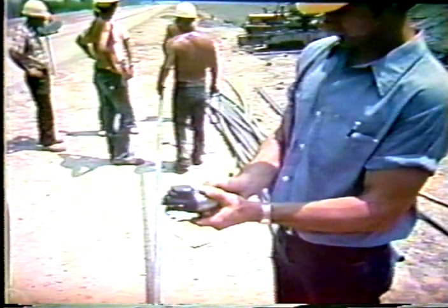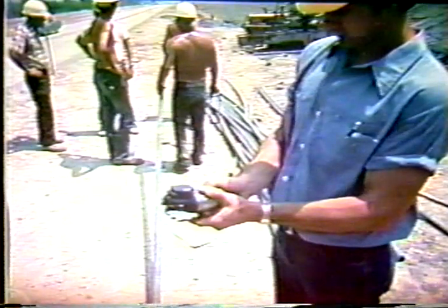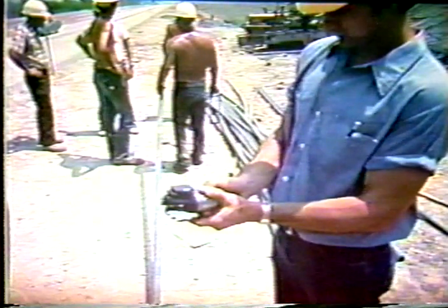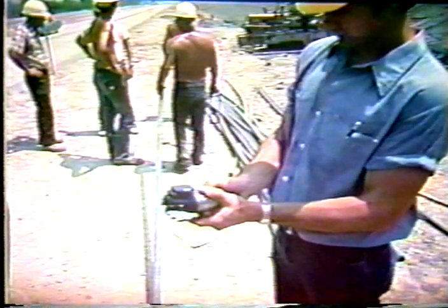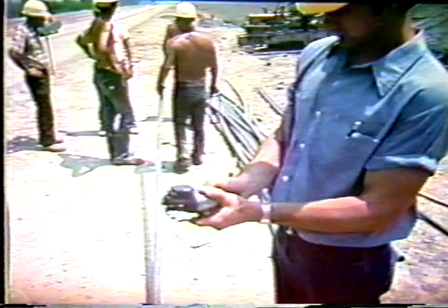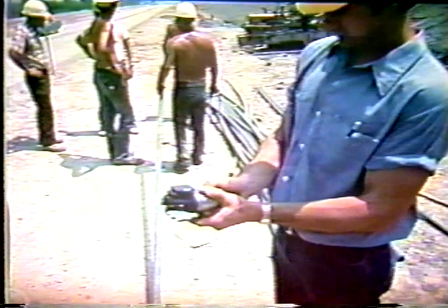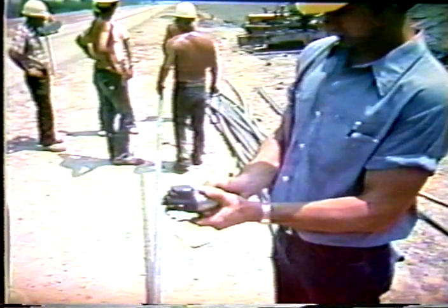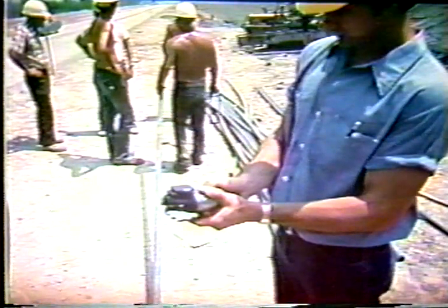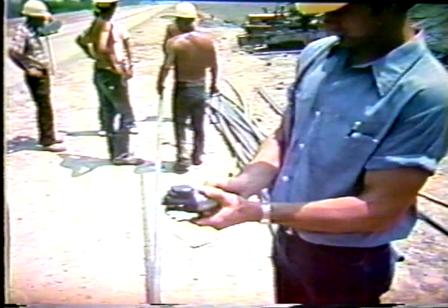They use a special type of disposable drill bit. In other words, the bit's mounted on the end of the horizontal casing, and they drill the casing in. They don't want to lose the casing, but they have come up with a disposable drill bit, so they just leave it in place. They just backspin the casing and pull the casing out. Well, first, before they pull the casing out, they insert the plastic pipe, the slotted pipe.